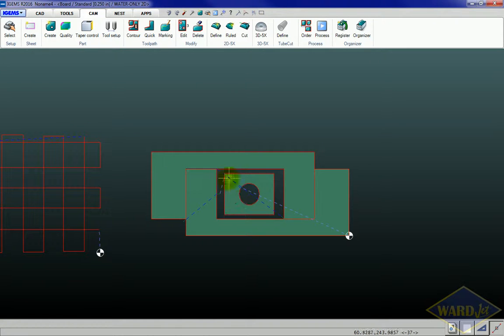what I might want to do is, again, probably for a water only application, after it finishes this rectangle here, rather than shut off, just keep the jet on, come over to here, and we could cut around the inside, cut out and then around, and we might have to shut off and then traverse over here and cut that. So it's another situation where you might be able to use the manual command and optimize things a bit.